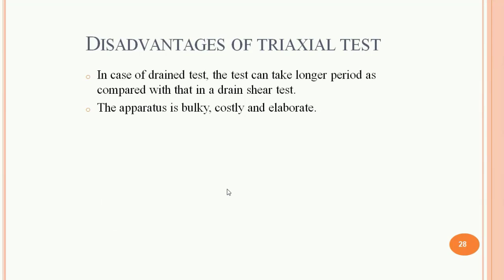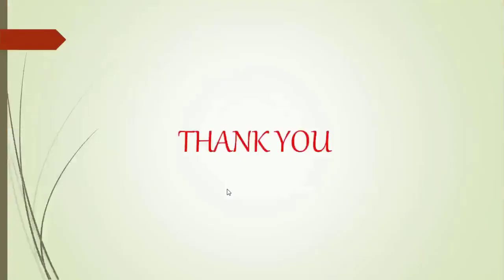Then the disadvantages of the triaxial test. In case of the drained test, the test can take a longer period as compared with that in the direct shear test. This apparatus, of course, is bulky, very costly and elaborate.